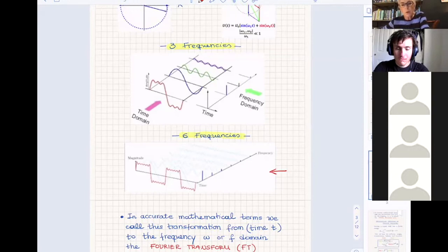So we will always use counterclockwise signals, but I just wanted to explain that the negative frequencies that you see have a meaning. There is a physical meaning to it. It's not just a mathematical byproduct or mathematical junk, if you like. They have a physical meaning. It's just that we always use counterclockwise signals, and then we superimpose those.